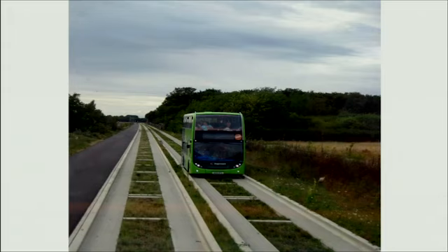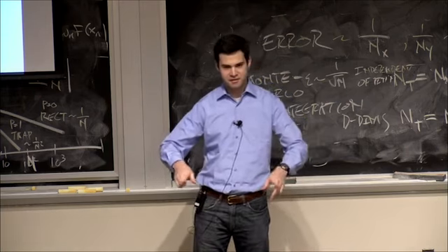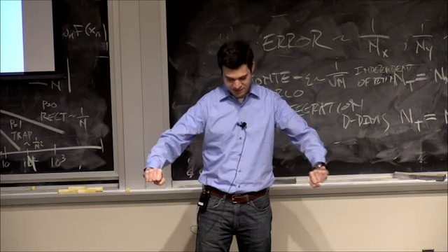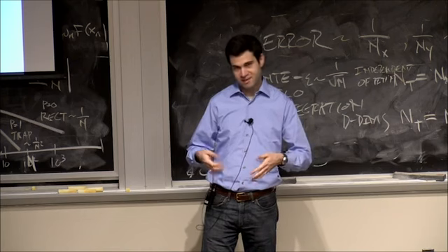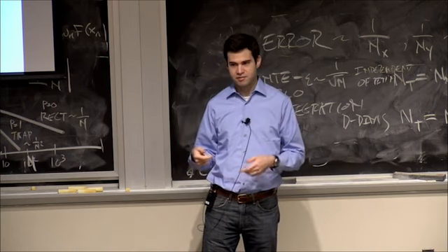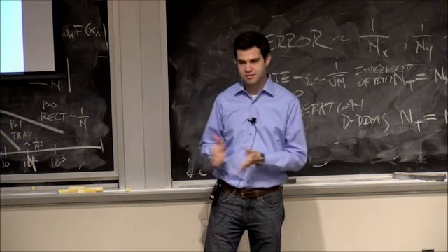So here's the Cambridgeshire busway in the UK. This is automatically guided. So the bus has a mechanical arm that sticks in front of the wheels or behind the wheels with a curb, and it sort of holds laterally against these edges of concrete. And so if that guideway turns, the steering wheel will also turn. Does that make sense? The benefit of this is that you can run quick, you can operate at high speed through narrow sections. This is more useful in tunnels. So, for example, the Silver Line here in Boston could operate much faster if it had that system to guide it.